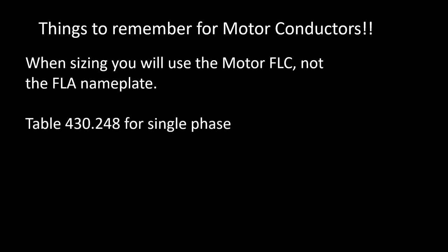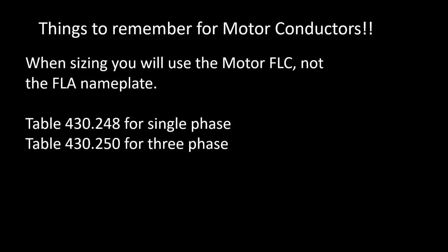All right, so when we're dealing with FLC, we have to go to Table 430.248 for single phase. This is assuming that you already know how to do this. If not, I have tons of content teaching you how to use that table. And it's going to be Table 430.250 for 3-phase. So just keep that in mind.